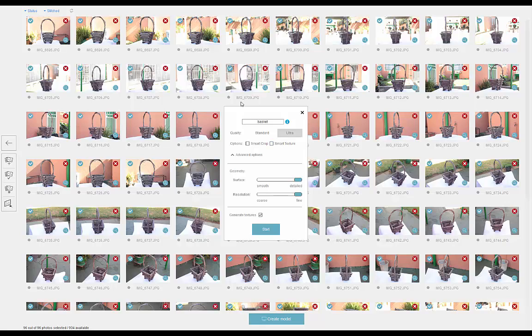And photogrammetry is a very CPU intensive process. So I've got 16 gigabytes of RAM, and I've got 96 photos. This will probably take about maybe 30 or maybe even 45 minutes to do the reconstruction process. So obviously the more RAM you have on your PC, the quicker this is going to go. So I wouldn't recommend anything lower than 16 gigabytes unless you want to wait really long. If you've got 64 gigabytes, awesome. This is going to be really quick for you.